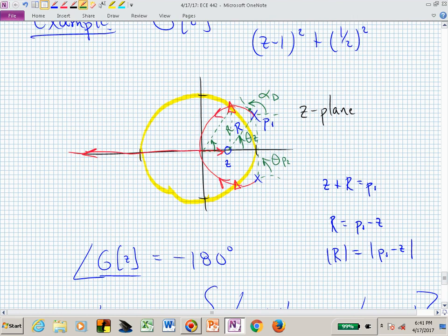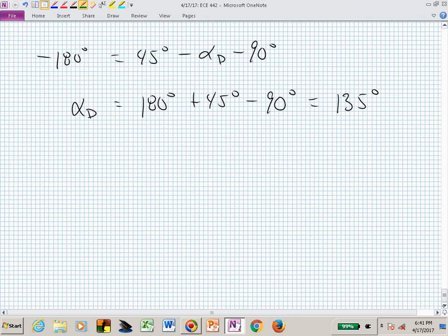Now, you've drawn this on the back of an envelope. You have a good feel for this, but you want it to be a little bit more precise. What might you do? Well, you might open up your computer and get into MATLAB, right? If you were in MATLAB, you could just say rlocus G, and it would sketch the root locus. Now, that's assuming that G has been defined. G is now a transfer function.